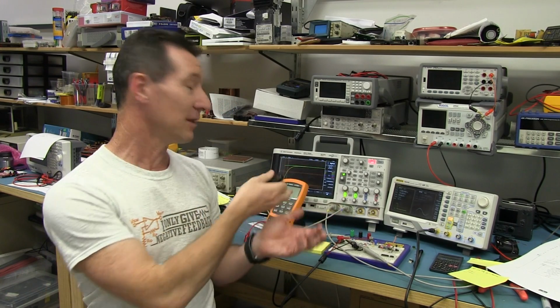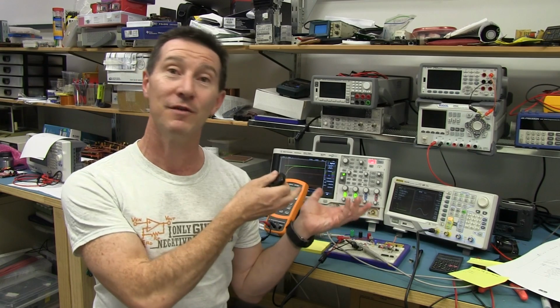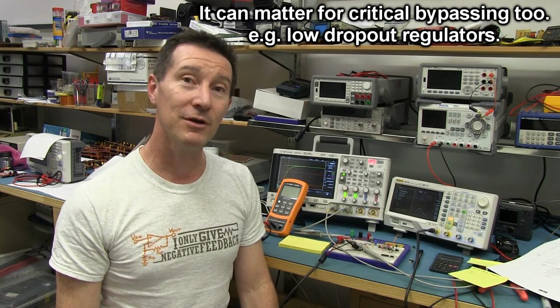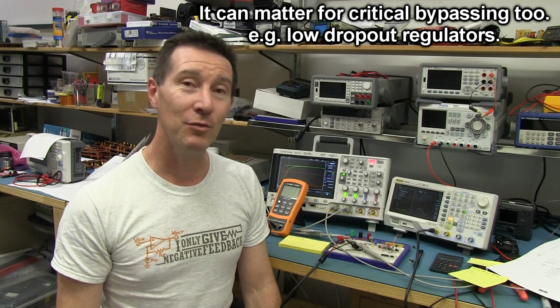So it's not just about RC time constants like this. Of course, if you're using the same circuit for filtering and things like that, it can really matter based on the signal level. It can be really quite critical. So you have to be very careful with how you use these modern ceramic capacitors.